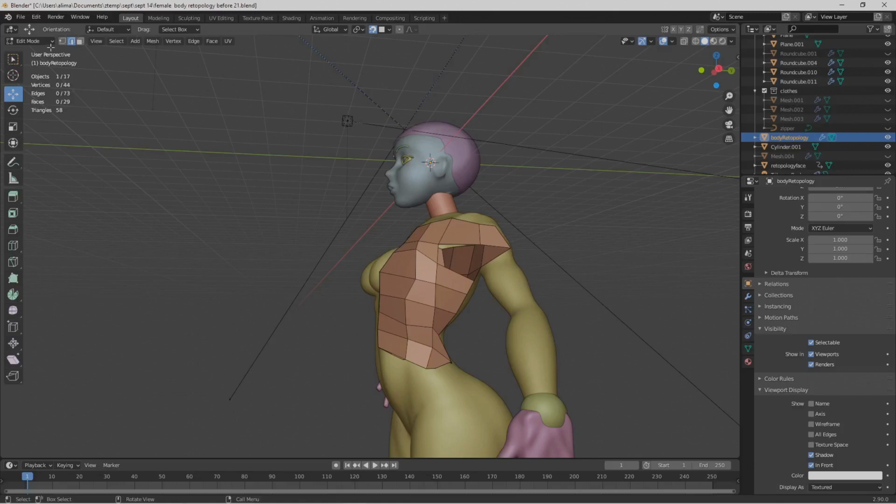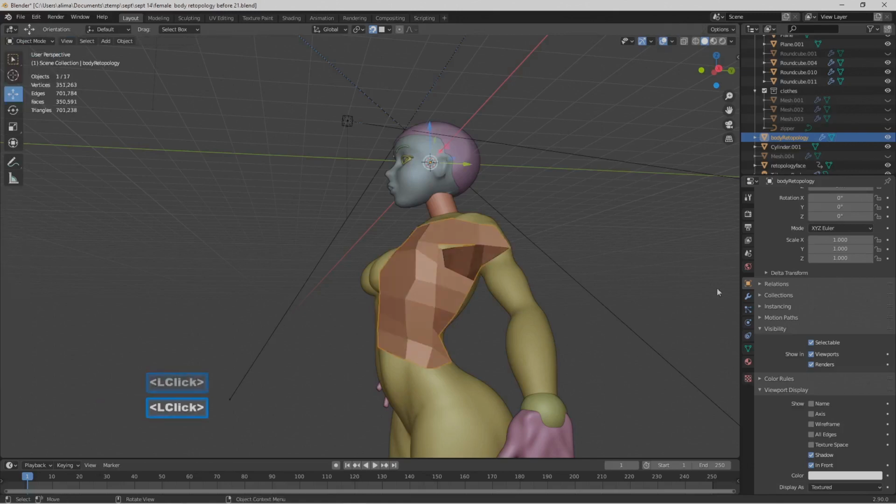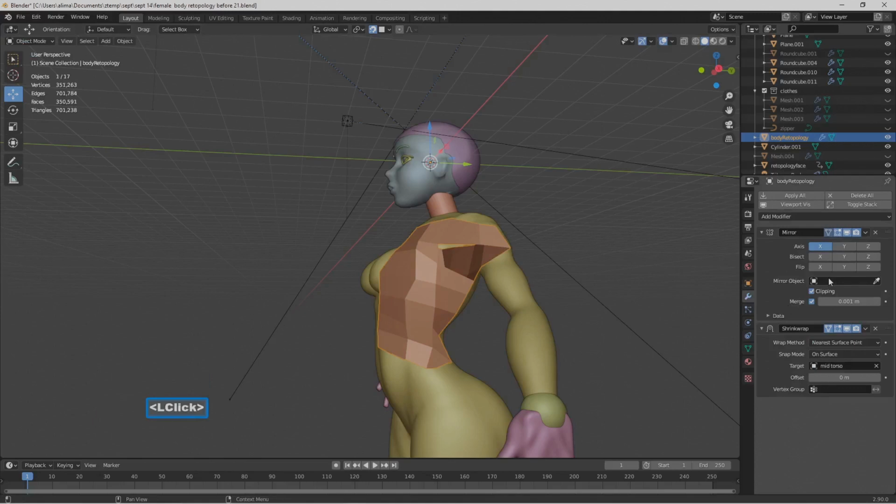Okay, we're going to go to the upper left to object mode. We're going to go to the wrench. We're going to go to the arrow to the right of the shrink wrap top options, select apply. We're then going to go to the middle of our upper screen, select the magnet to turn that snapping off.